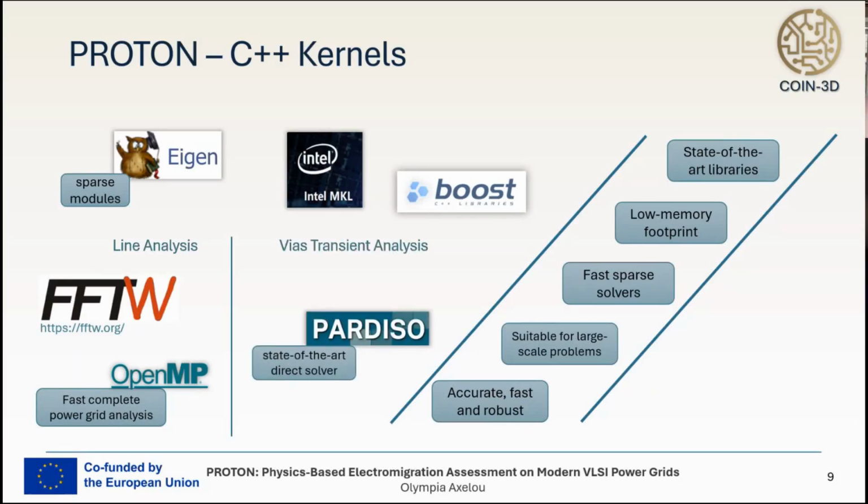Now, as for the Krylov transient analysis, the internal steps utilize the PARDISO solver, a highly optimized and widely used direct solver for large-scale sparse linear systems. The solver ensures robust performance, which results in reliable solutions and efficient memory usage, something very important for EDA tools.